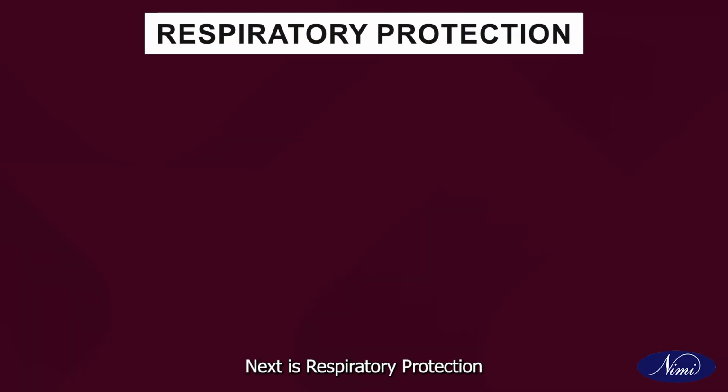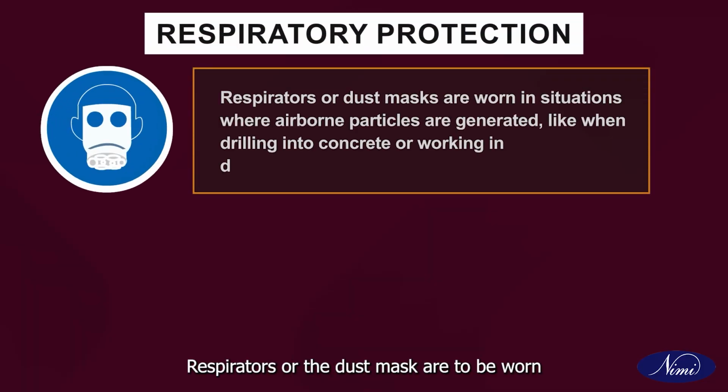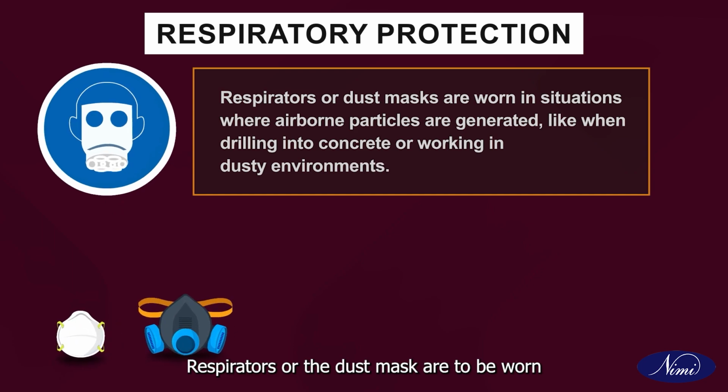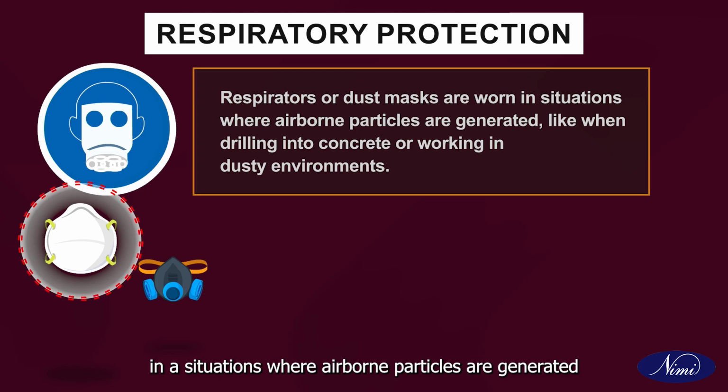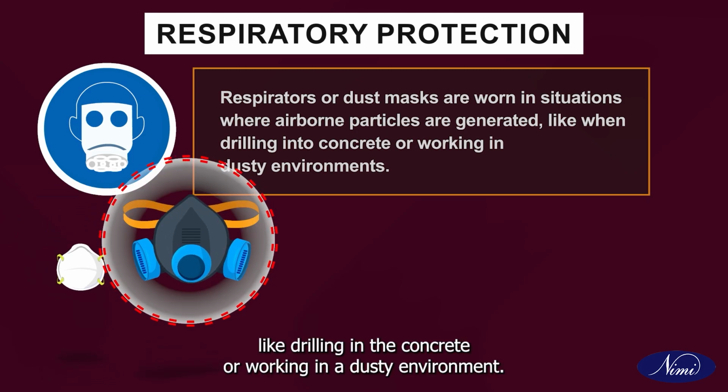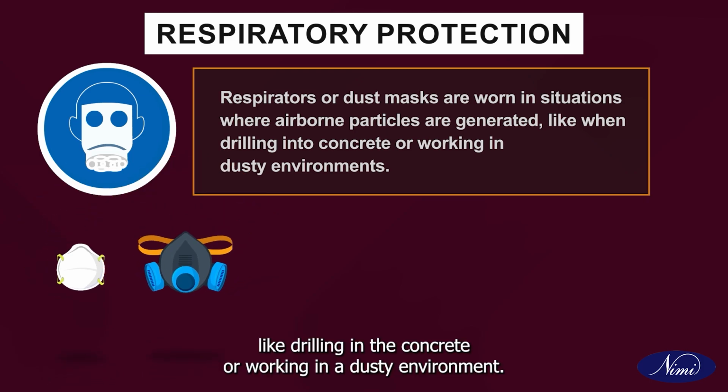Next is respiratory protection. Respirators or dust masks are to be worn in situations where airborne particles are generated, like drilling in concrete or working in a dusty environment.